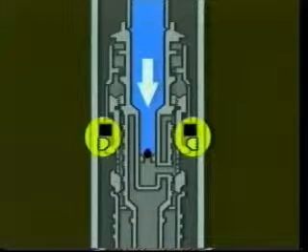At the setting depth, the tripping ball is circulated or gravitated into place on the ball seat. Applying pressure will actuate the setting tool, causing the packer slips to engage the casing and the element to pack off. Increasing the pressure will shear the ball seat, opening the gravel pack port. After setting the packer, the setting tool crossover assembly is released from the packer with right-hand rotation.